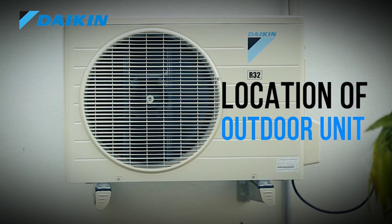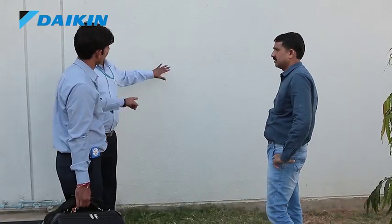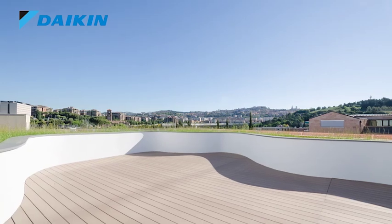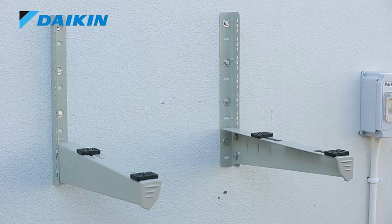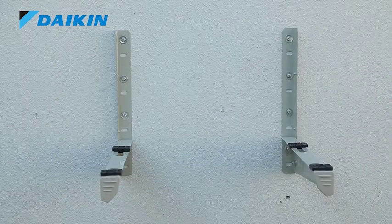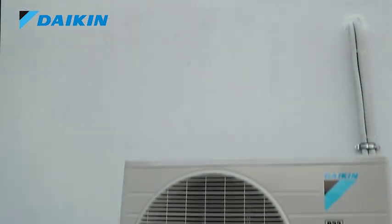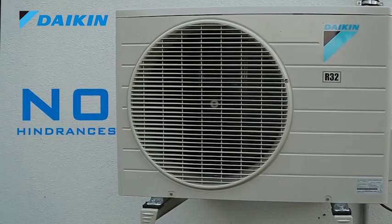Location of outdoor unit. The outdoor unit should be located in open space, preferably on the terrace, so that air can flow freely. If terrace is not available, it can be hanged on the external wall supported by angles. If using this stand, proper anchoring of stand must be done to fix it properly on the wall. Ensure that there should not be any hindrances in front of the outdoor unit that would block the passage of air from passing to open air.